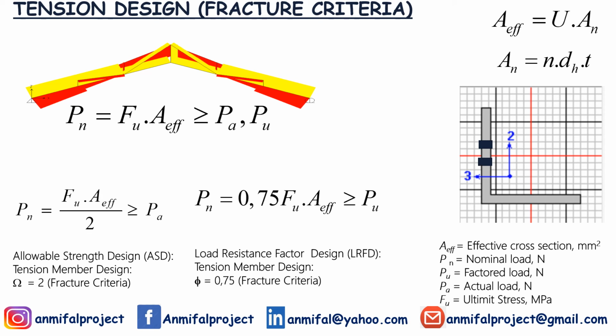Then what is the net area? The net area is determined by multiplying the number of bolt holes by the hole diameter and the thickness of the member.